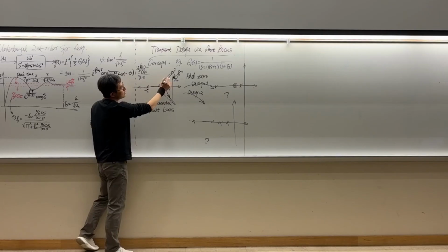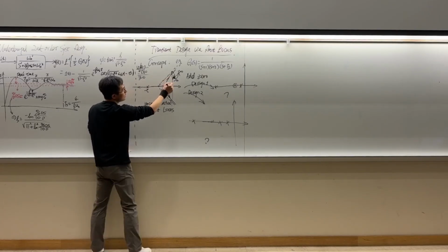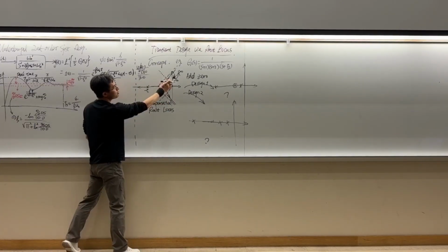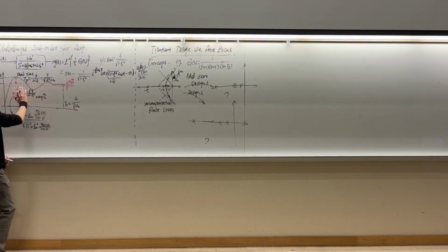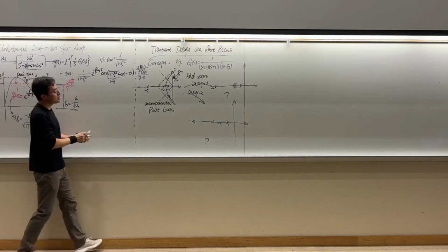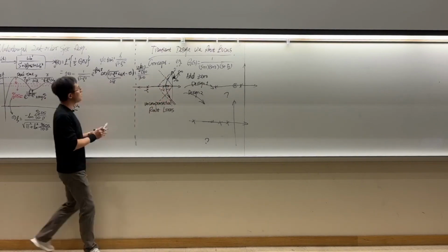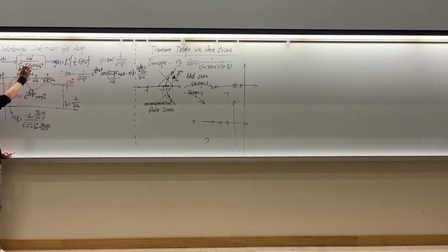Now, the root locus is showing that we're going to have complex closed loop poles, and we can correspond the time domain responses of a complex pole like this to the time domain responses, right? We already cleared that this is less dominant. So the dominant system behavior is going to be like a second order system.